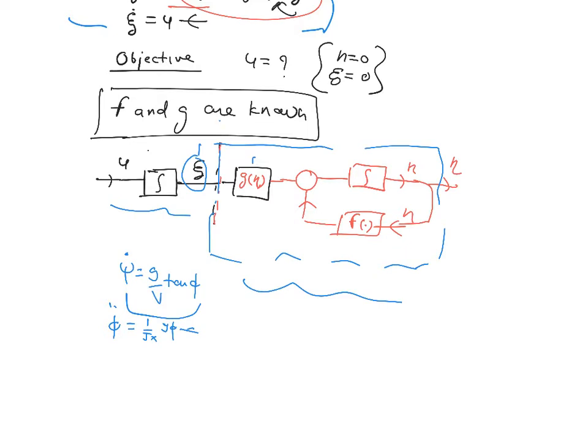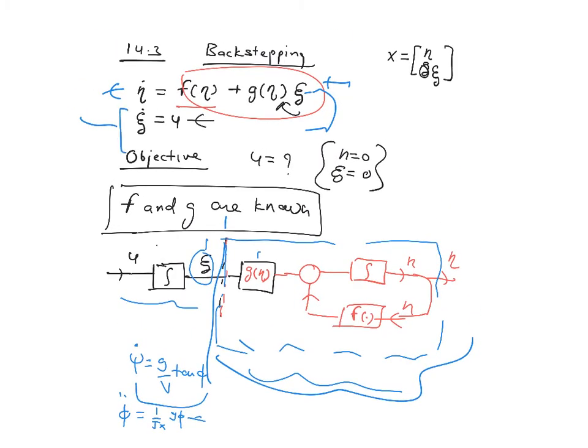So you break down the problem now. We want to solve this problem first. What is this problem? What if you forget about this, and you just deal with this first equation. In the first equation, zeta is considered as input. So you want to compute what should be my zeta, what should be that feedback law such that eta goes to 0. Simple as that, right? So there it's easier. Now you can choose a simple Lyapunov candidate function, which is half eta transpose eta, or half eta dot square. And then we'll go from there.